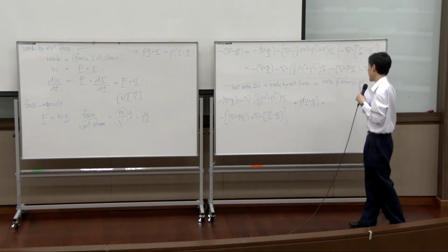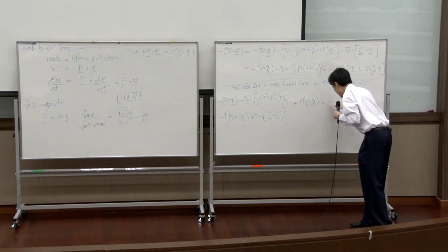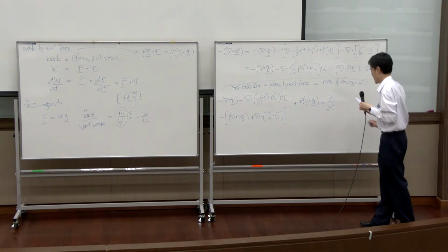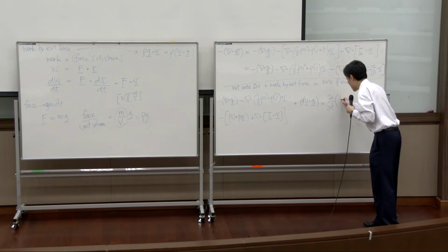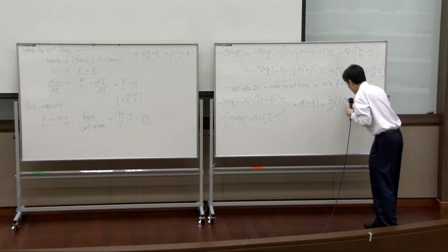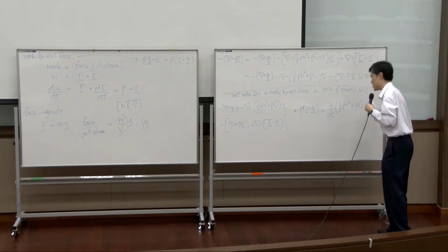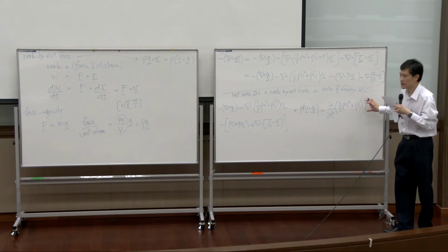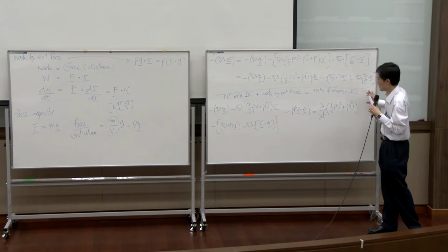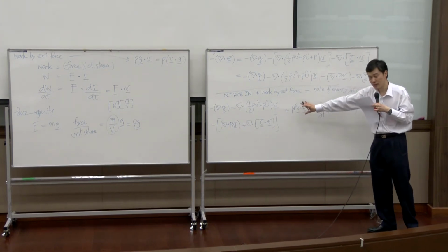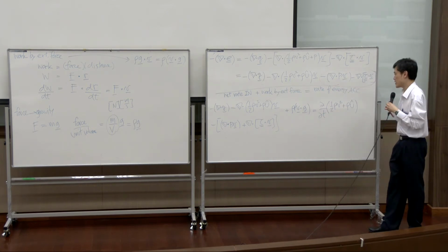Equal to rate of energy accumulation. Energy accumulation is basically change of energy with respect to time. And energy here is supposed to be energy within the system. It consists of kinetic energy, internal energy, and for the moment, I want to keep potential energy away. I will prove in a minute that potential energy is already there somewhere. So this part would be energy accumulated in the system.